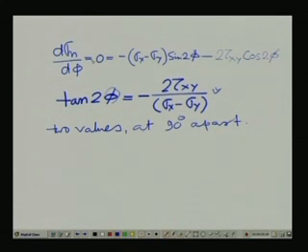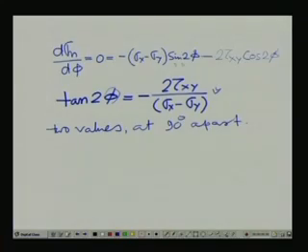the shear stress tau. That means whenever the normal stress values are maxima or minima, under those conditions the shear stress values come out to be 0, because this expression is exactly the same as the shear stress expression we derived just earlier.